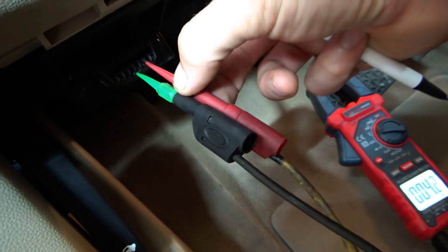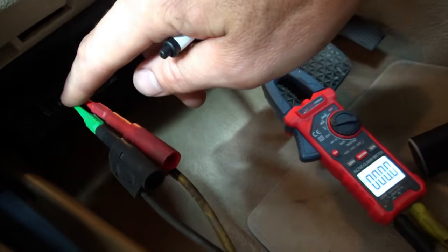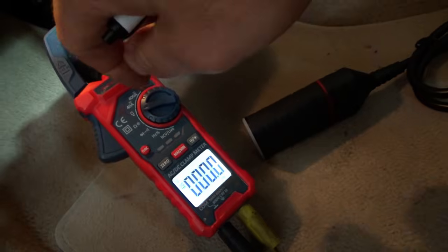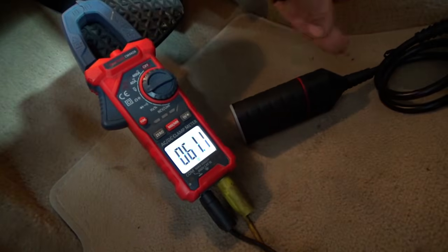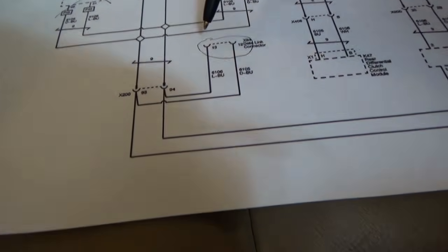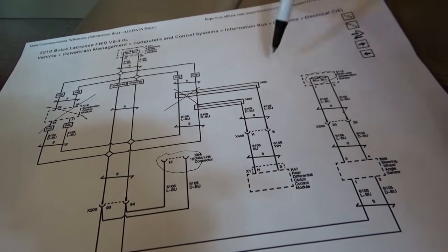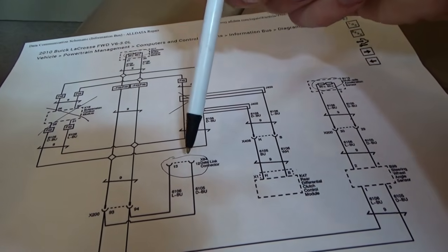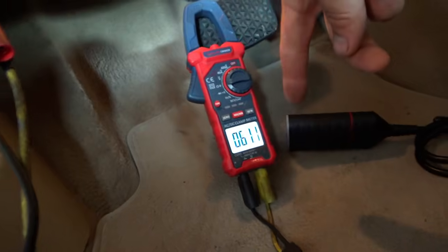So I think now we can do our resistance check. See, there's 0 millivolts between those 2 pins now. Right there. So let's go to the resistance reading. 61 ohms. So that tells me, hey, we don't have any broken wires all the way from here through these terminating resistors and coming all the way back to our meter on the other pin. So that's good. Now, keep it in the ohms scale.